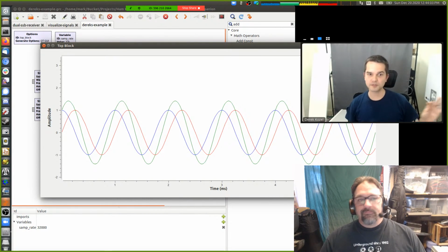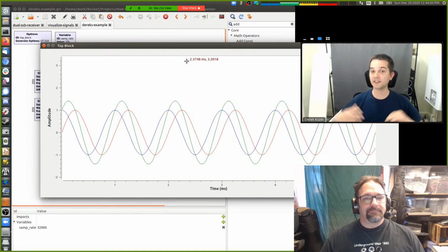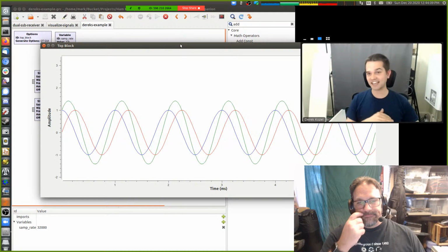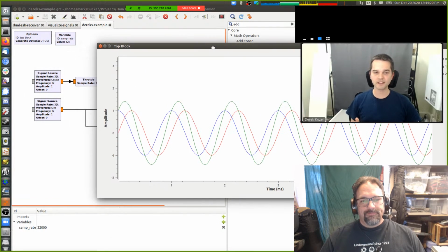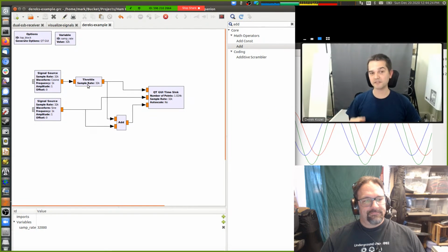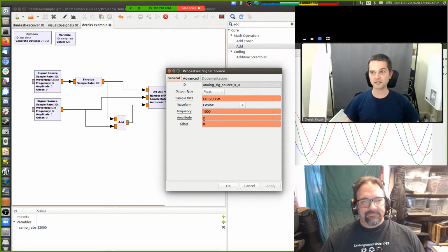But yeah, cool. Okay, so we have two input sine waves. We add them together. We get another sine wave. The frequency of this sine wave has not changed. It is still a 1 kilohertz sine wave. The amplitude of the resulting wave is larger. And the cool thing is that the power of a signal is the square of the amplitude.